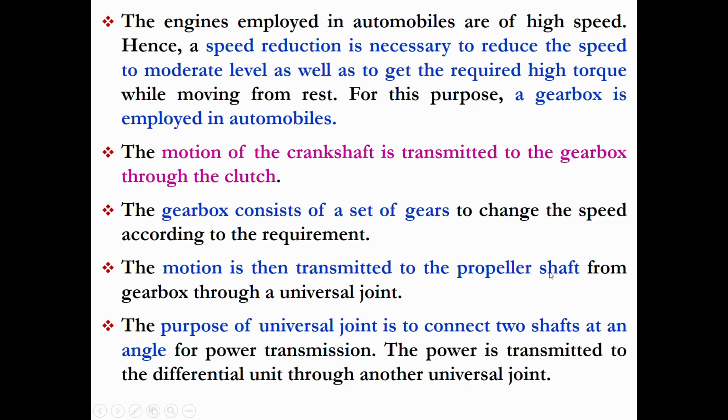Normally at very low speeds we need a higher torque to propel or move the vehicle, but at a higher speed we need very little torque. So by reducing the torque we can increase the speed of the vehicle. But from an idle state or a stop position to a slight, very slow movement, we need a very high amount of torque. This change between torque and speed is taken care of by the gearbox.